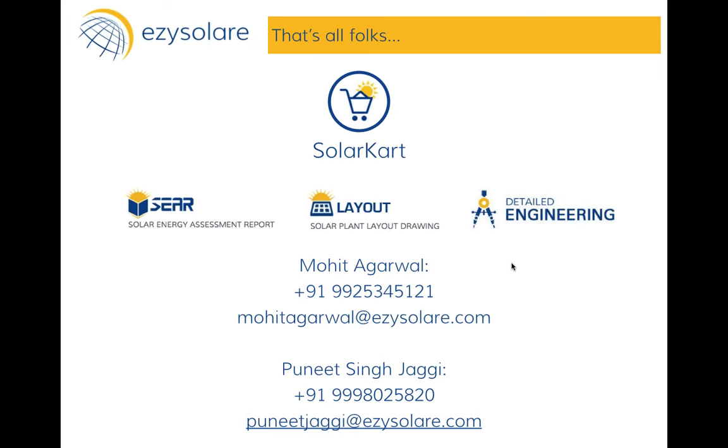Are the solar panels connected in series or in parallel? Probably Shivya, if you could answer this. In one string, we use the solar panels in series, and different strings are connected in parallel. So we have both, series as well as parallel. In one string, we have the series connection of panels, and the strings are connected in parallel with the inverter.